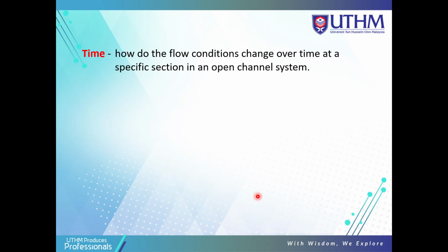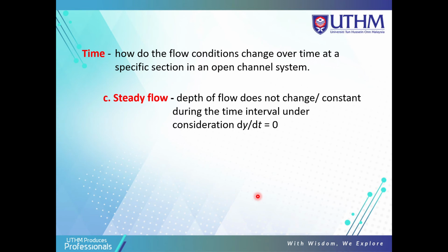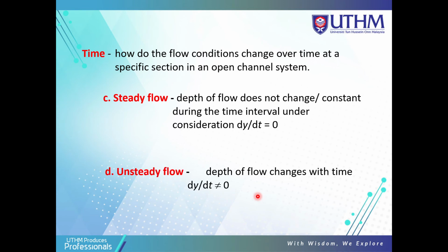Now for time, how do the flow conditions change over time? We use dy/dt. In steady flow, the depth of flow does not change during the time interval under consideration, dy/dt is 0. In unsteady flow, the flow changes with time, dy/dt is not equal to 0. Just remember that for space, you must know uniform flow and non-uniform flow, but for time, steady flow and unsteady flow.